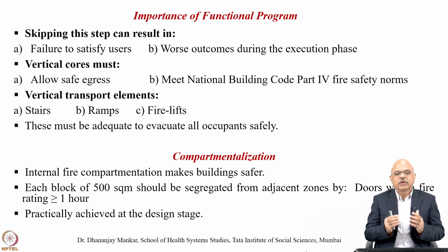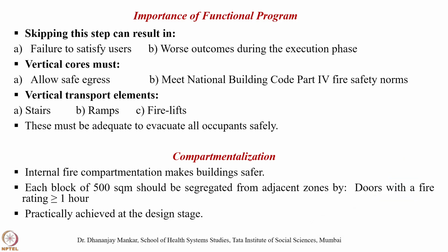Compartmentalization. Internal fire compartmentation makes a building very safe. Each block of 50 square meters should be segregated from the adjacent zone. Doors with a fire rating of more than 1 hour are practically achieved at the design stage.